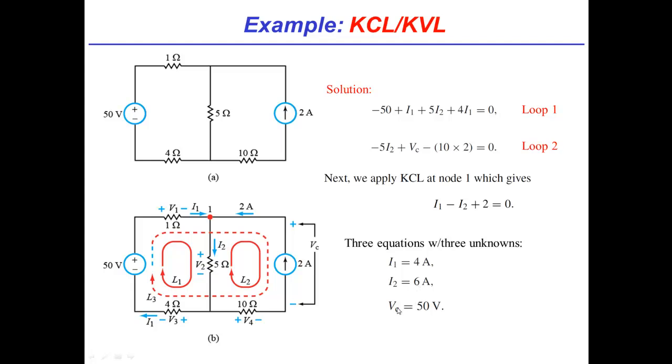Exactly. And you can do that with VC. VC is kind of weird to some of you. You're like, 50 volts, what a huge voltage. What do I do with that? Well, we've made up this problem, so these are strange numbers. But you can go ahead and do KVL around. I'm not going to do it, but you could do a KVL around a loop. Now that you know all the currents, just multiply the currents with the correct polarity times the resistances and go around, and make sure that if you go around everything here, say starting at this point, going over here, going up, and coming back, adds up to 50. I mean, you'd know that you're consistent.